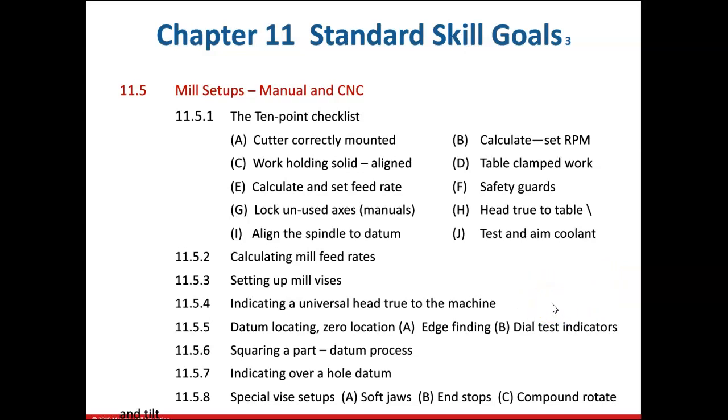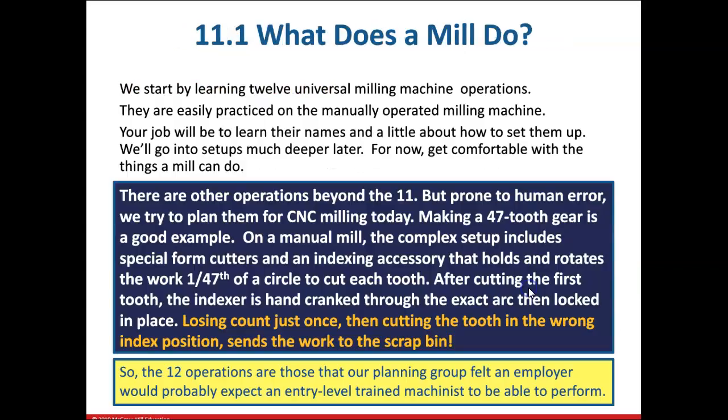If you just have a raw piece of material and you need to machine basically a perfectly square block out of that. If you think about what we would refer to as a 1, 2, 3 block, there's a method to machining each side of that block to get it perfectly square and parallel within a couple of tenths. And you got to follow the correct procedure in order to do that.